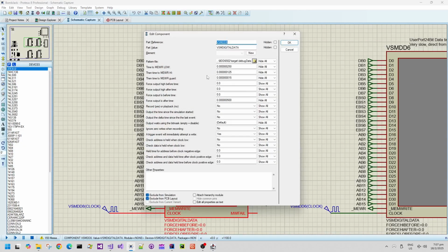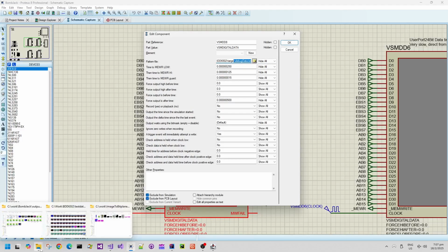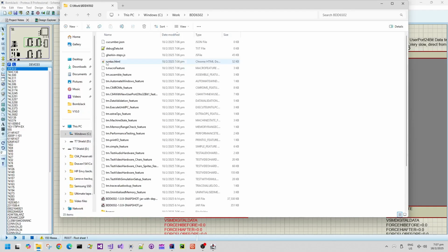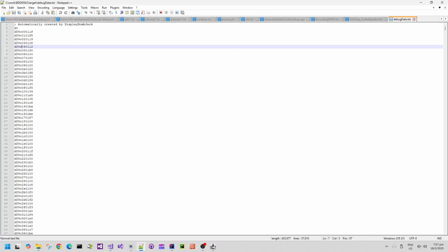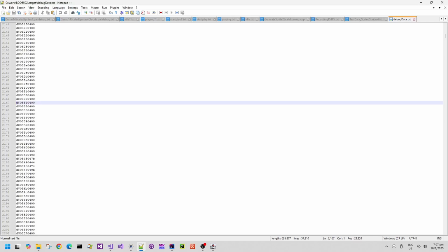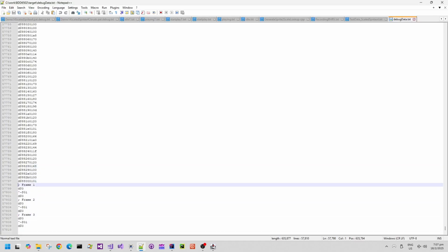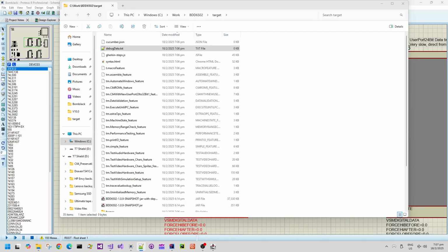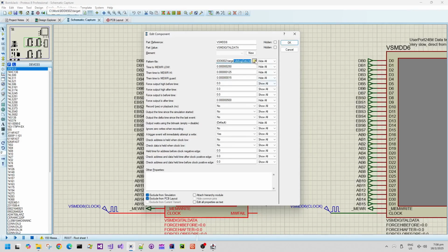I've just been using the standard small test data, so I can tell the simulator to pick up the debug data that's saved out from the Java software-based emulation of this MegaWang 2000 Turbo Edition hardware stack. And whenever it runs, it can be instructed to output all of the bytes that are sent over the user port, all of the bytes that get sent to the video hardware. So it stores out a 24-bit address, and it also stores out the byte. And that's what those $D instructions are, or debug lines in the debug data output there.